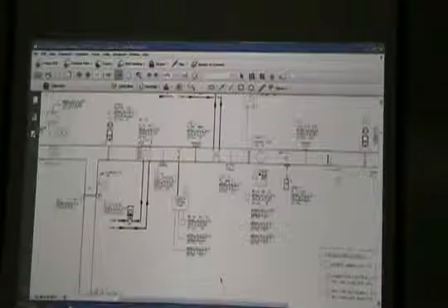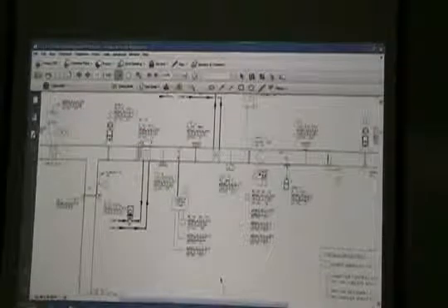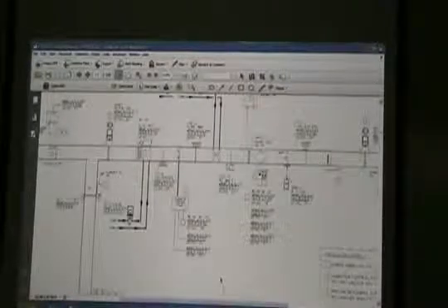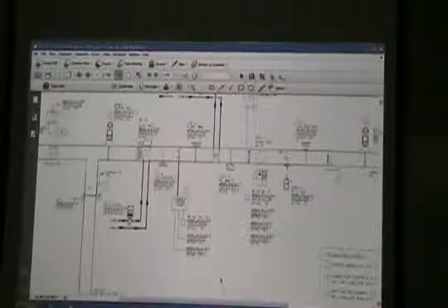Okay, so probably in that air handling unit, from there to there, a coil that tall gives us 500 feet per minute. But in a heating coil that's sensible only and has no condensation, we can go to 800 feet per minute. So right there, I don't have to modify my air handling unit at all.